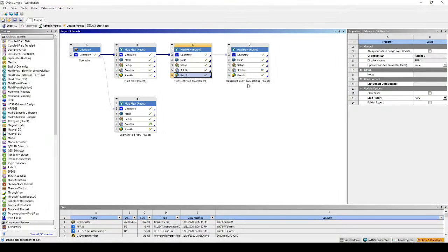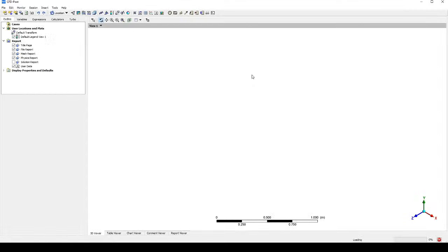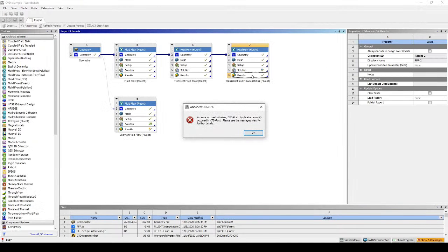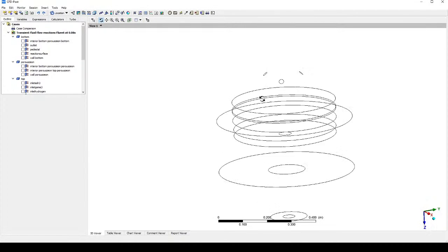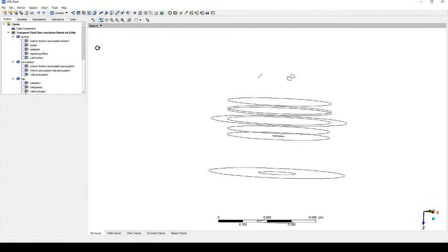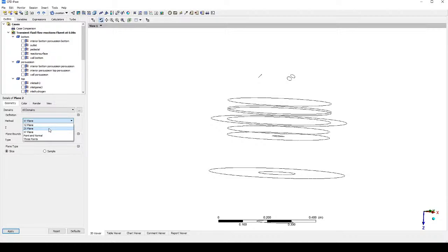Transient analyses tend to be orders of magnitude longer to run than steady state simulations, so you definitely want to use transient simulation sparingly. The other thing is that we often use a steady state result to initialize our transient simulation. That gives better convergence, and you can save a lot of time in terms of getting rid of the initial maybe transient flow behavior.